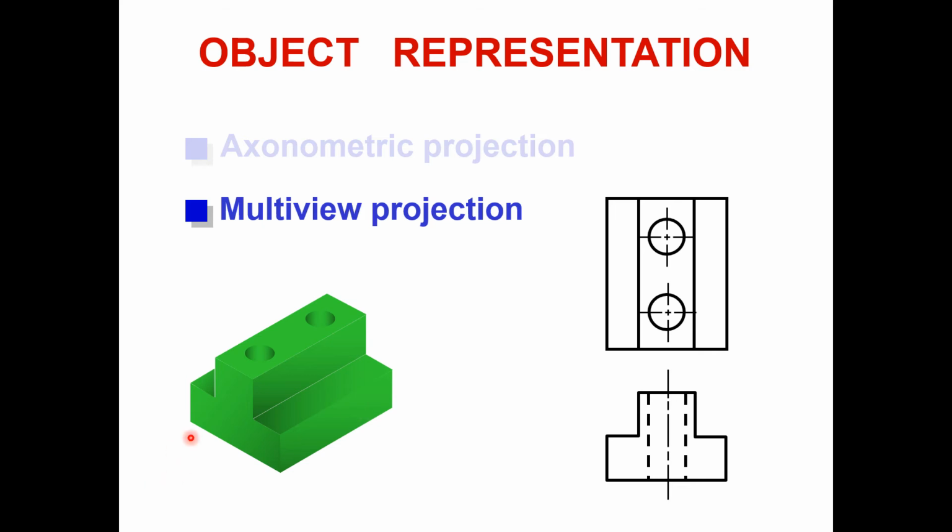When you see from this side, you will see this solid face, and you also know that there is some hidden feature, like a circle behind this. To show this circle, we use the dash line for showing the hidden object. So here at the same location, dash dash dash, similarly here, that shows the location of the hidden feature, and for the circles the center line is shown. So that is the multi-view projection under the subheading of orthographic projection.